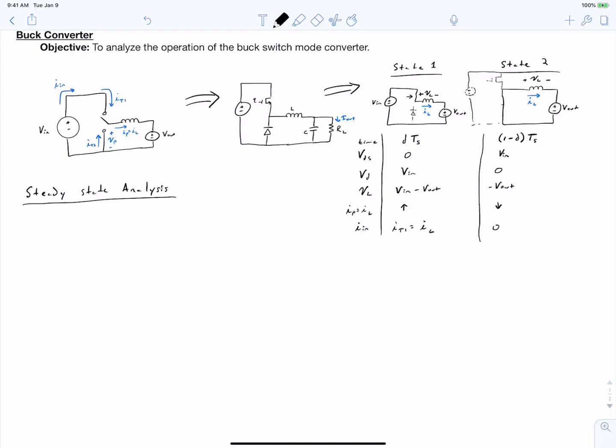As we previously talked about, the voltage across the pole of the single pole double throw switch is going to be equal to the duty ratio of the pole connected to the top throw times the input voltage. So Vp is equal to D times Vin, where D is the duty ratio of the MOSFET, or in other words, it's the duty ratio of the pole being connected to the top throw. And the average value of this is simply equal to our output voltage. This is an important expression for the buck converter.